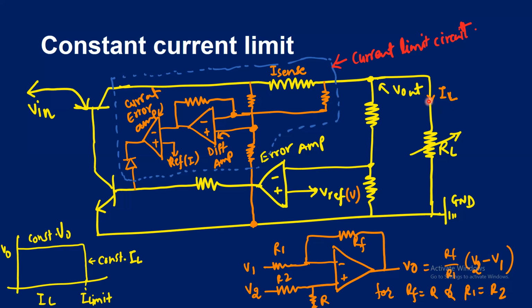So if you operate that particular IC below 250 milliamperes as an example, you can source that value of current as long as your output is in the range of, let's say, 1.25 to 30 volts, and the input voltage should be at least, let's say, 1 volt above the output you choose. So if you choose 1.25 volt output for delivering a current of 250 milliamperes, your input would be 2.25 volts, just at least 1 volt greater than the output.